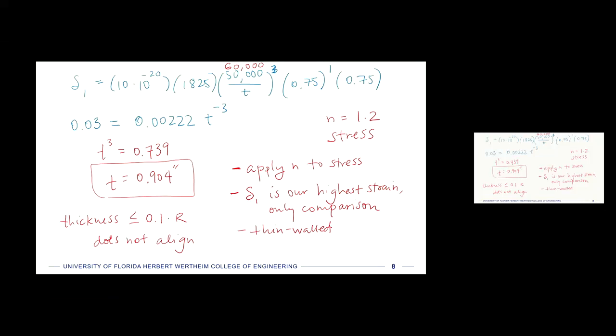So the first thing that we could do is apply the safety factor to our creep strain instead of a stress, right? So we're assuming that our stress doesn't change. The pressure vessel is pressurized, stress stays the same. What we have is constant stress and high temperature, right? And so we get this creep elongation, and that's what leads to our failure.